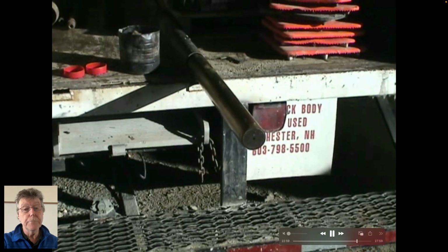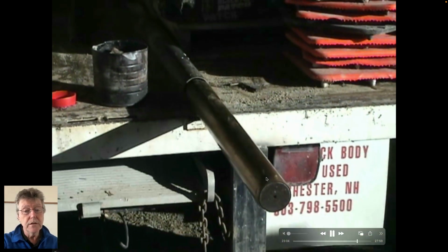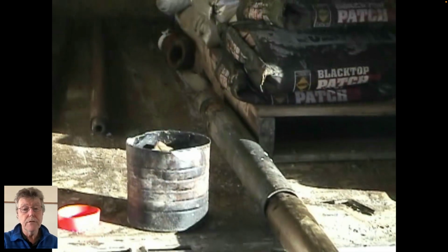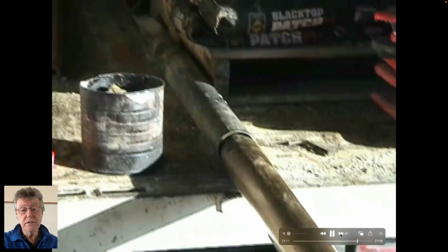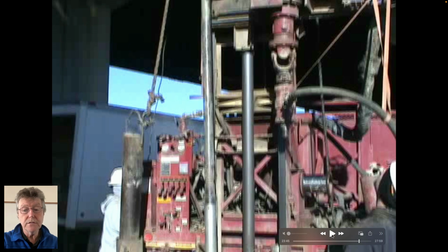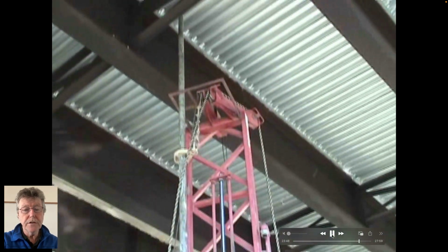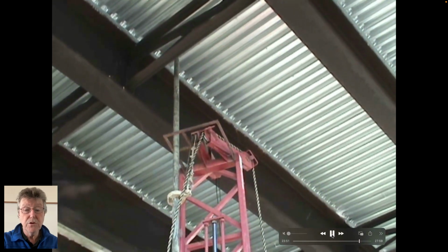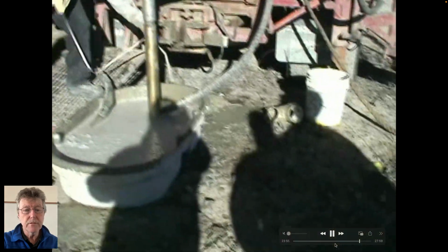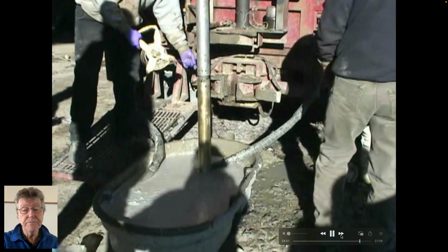So this is the piston sampler, the pictures that you saw already. This is the Shelby tube that's already added onto it. I guess Shelby is someone's name. Ready to be deployed in this particular case. And this is it being deployed, I guess. So lift it up into the mast. Don't know why that bit goes so high. Measure how deep the hole is with a tape measure. That's all that's being done there.